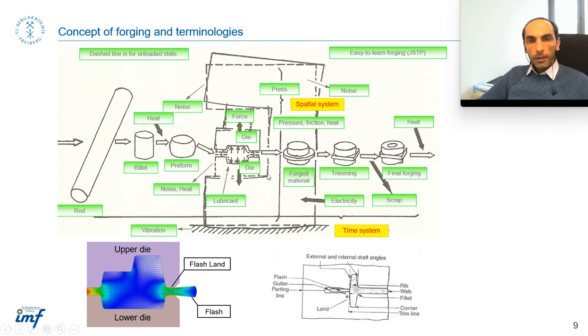And then after forging, this is the forged material, and this part we call flash. I talk about it here in detail. Usually forging is not one stage, usually preform and then 2-3 stages, maybe it depends on the design. And then you have a flash here. You should trim the flash, remove it, because it's not in the design of the workpiece. It should be removed, and then finally some heat treatment, and the final product is ready.